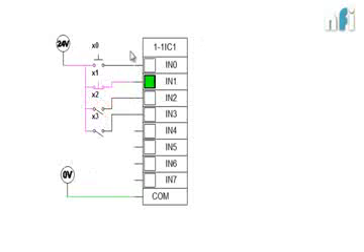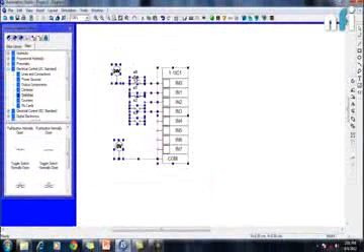Now I hope you have understood that this is on because this 24 volt is already across this terminal IN1. This will be on when I press this button, and again similarly with these cases. So this is my input section, how we are getting the inputs from the outer world and how this PLC is judging the inputs just by this voltage. Again, where you're going to have potential difference, that input will be on. So this was about the input card of a PLC, or you can say input terminals of a PLC.